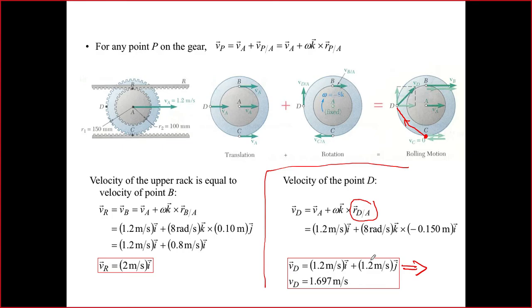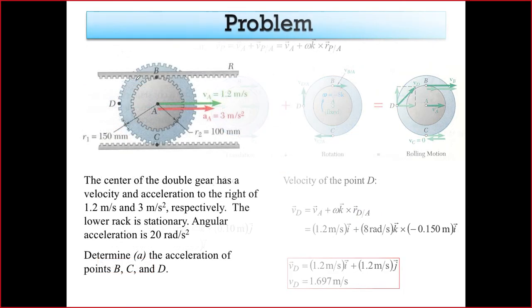Okay, so please note that C is the instantaneous center of rotation. So VA moves horizontally, VB moves horizontally, this upper point also moves horizontally. All of these are going to be, sorry, I should have made them proportional to the distances. Next, D will move perpendicular to the line joining D and C. So that's going to be in this direction and so on. Straightforward, I think. Now let's jump to the accelerations.